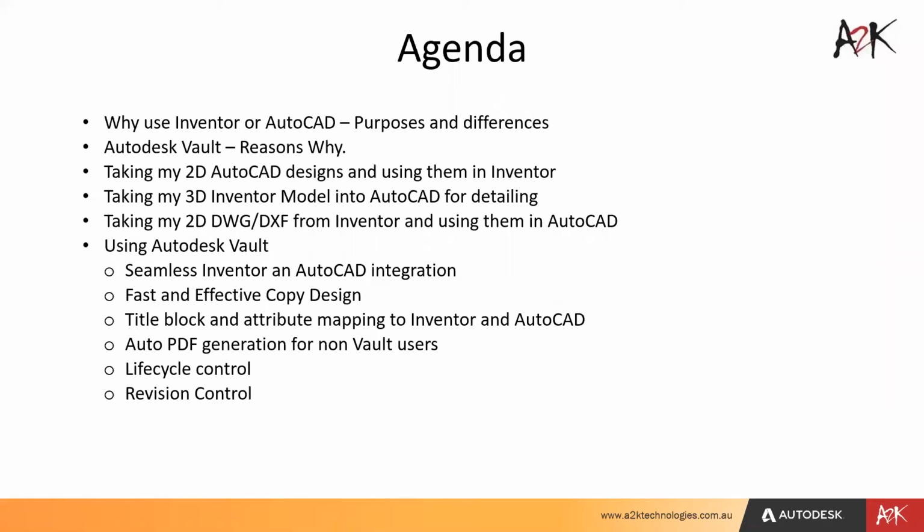Having a PDF automatically created at a lifecycle transition, and how that can be exported out to a network location, or how it can be viewed within the thin client. And then we'll talk a little bit about lifecycle control, revision control, version control, and just a little bit of an overview of what Vault can do.